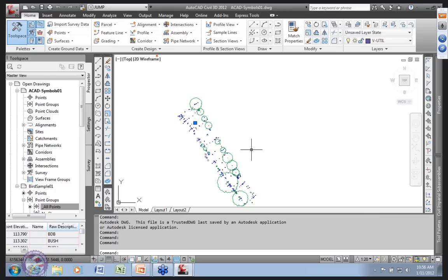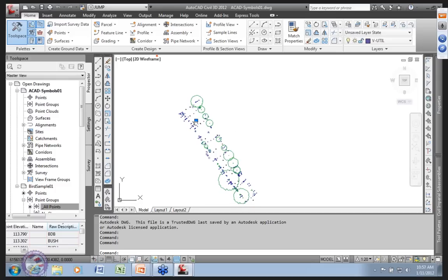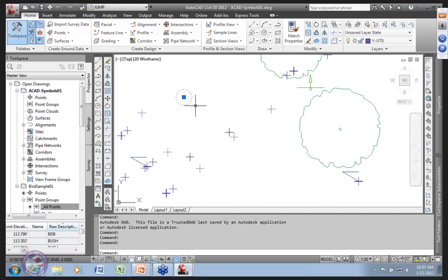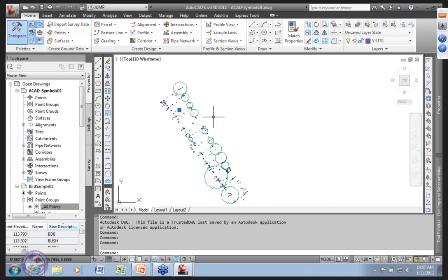So anything in terms of any Civil 3D stuff that might have been around it, right, is all fixed to it. So if you did the labels and the symbols at the same time in your drawing, they would all be wrappered in this little beast. And that's what the export process does to preserve their location, since the meaning, right, of what this little symbol looks like is pretty important.